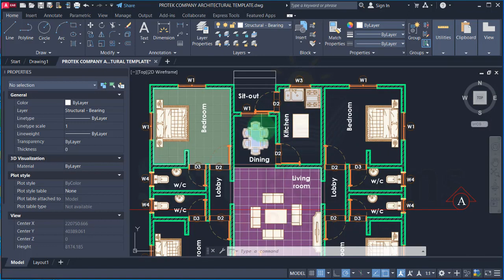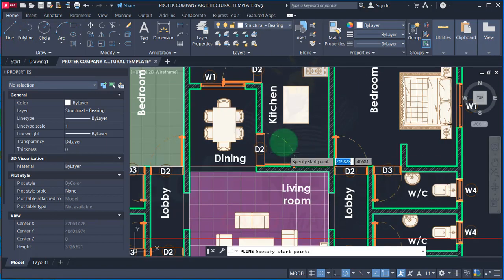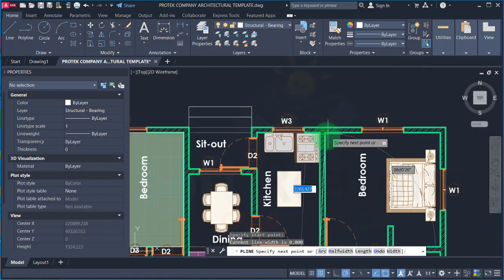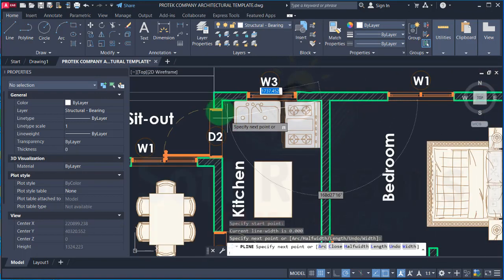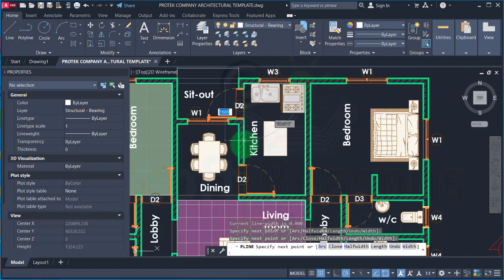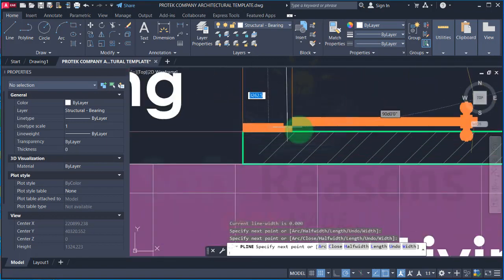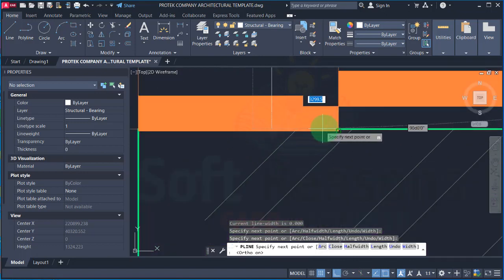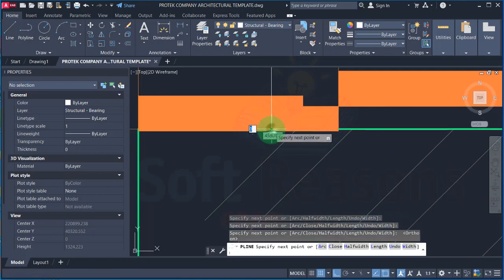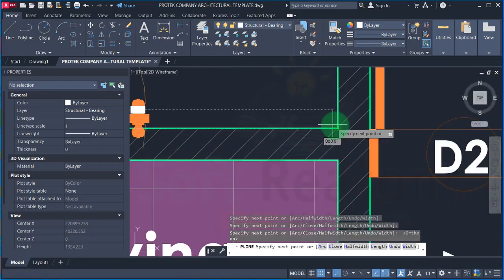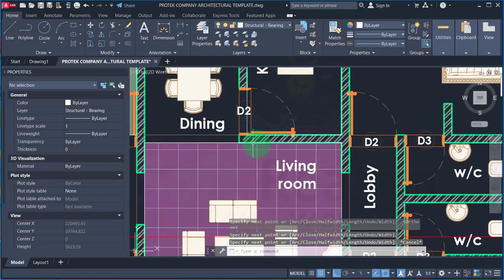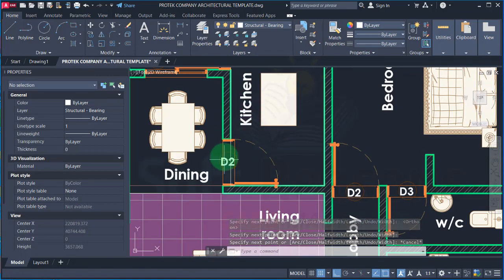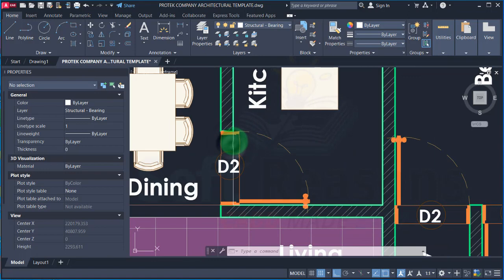At first, you have to use the polyline to mark out the provisions that you want to tile. Let me pick that point, and then over here I will pick this point, pick this particular point, and I will make sure I activate my ortho so I can have a very straight line. I'll pick that point which is correct, and then pick the last point. After you must have picked the four corners that make up this kitchen, just select the line that you created.